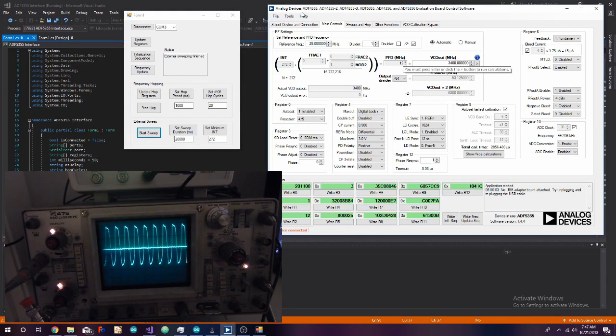The voltage that you see sweeping up and down on the oscilloscope is the external input generated by the external frequency synthesizer. Now this waveform is a triangle wave going from 0 to 5 volts, and this will be controlling the frequency output of the ADF synthesizer. To control the frequency sweep, we have to set the frequency output to the maximum peak frequency value.